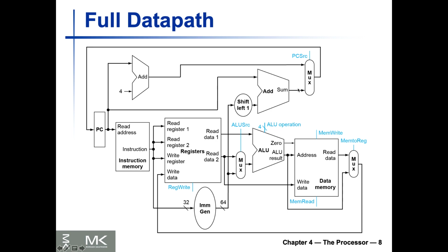If you want to integrate the target address for a branch, if you were to go to a target address, we actually need an additional multiplexer to send us to the target one. But in the current design, as you see, it's going to come back here to the PC, and if we decided to go somewhere else, we need another multiplexer. But this is a very basic processor that is only able to do load, store, memory, and branch.